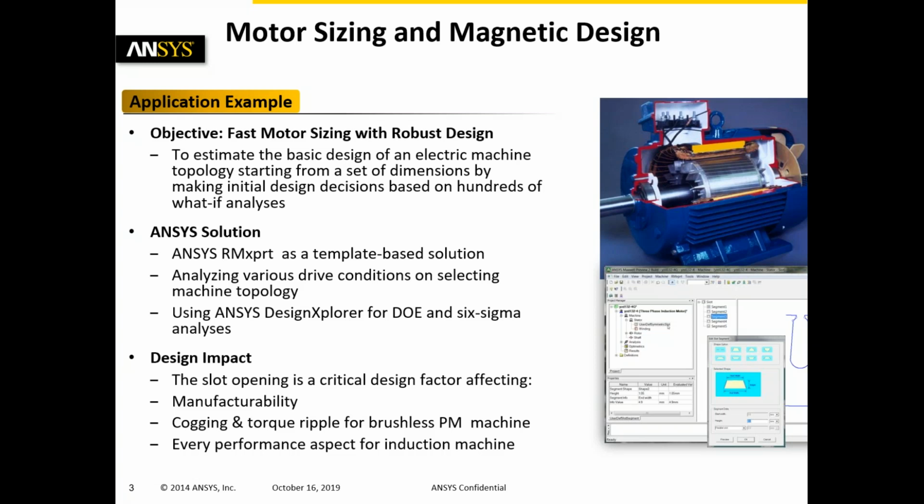So the ANSYS solution in this case would be we start with ANSYS MExpert as a template-based solution. We'll get into the details of MExpert in just a couple of minutes. After using MExpert and creating the template, we will analyze the various drive conditions on the selected machine topology. Then we would use ANSYS DesignXplorer for design of experiments and Six Sigma analysis